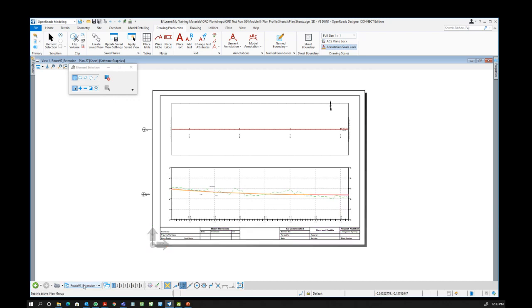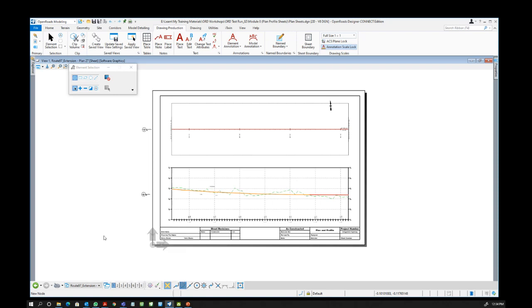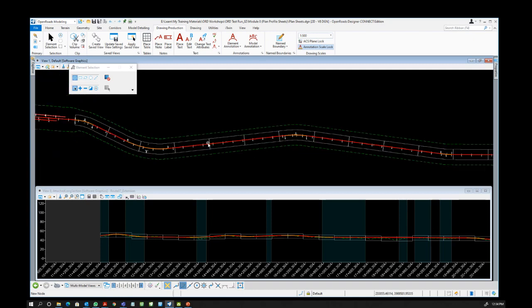Okay. If you want to go back to the main model, I click. Then inside here, you will scroll up and look for multi-model view. That, and then you go back. Now, if you want to update the references, because you want the corridor to show up, and maybe if you have other objects added, kindly just attach.